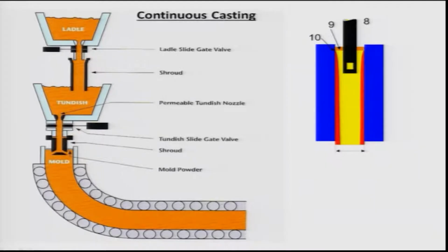So this is basically a chilled zone in which the liquid metal has been solidified very rapidly, because it's copper and also water cooled, so the heat transport is very high. So the number of sites on which nucleation can happen is also very large. Not only that, because it's a rapid cooling process, the sizes of the grains which may form along this interface are very small.